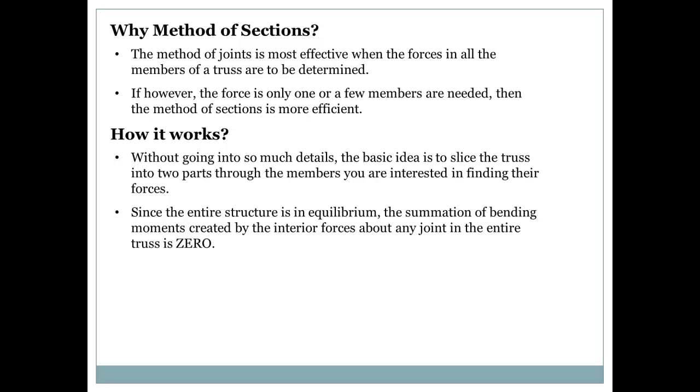The interior forces of the members that you exposed by cutting the truss create moments, and we will see this in more detail later. The summation of these moments about any joint of the truss should be equal to 0.